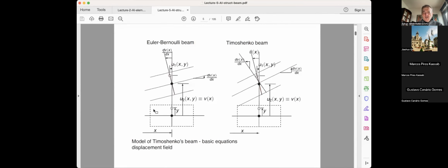So here's this illustration. In the initial configuration, this is the part of my structure, just a 2D picture. This is the so-called neutral axis, typically located at, let's say, the center of gravity of the cross-section. It's a fiber that does not extend during pure bending. That's actually how you define your neutral axis. And then if I want to describe the displacement of any point, which is initially at a distance y from my point on the neutral axis, first of all, I can have an axial deformation, but this will just bring me my truss bar element, so nothing new to learn there.